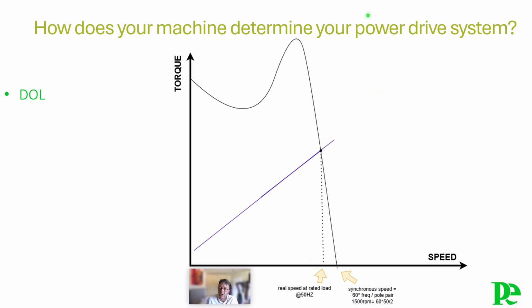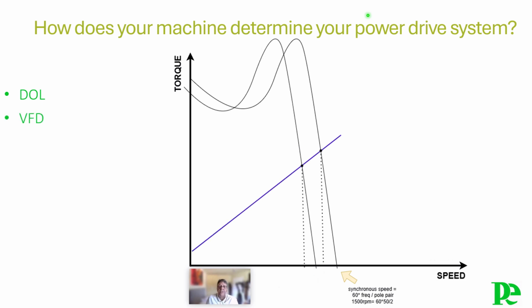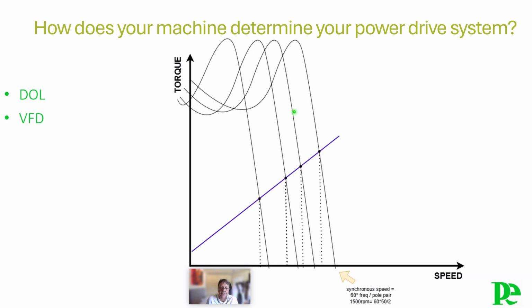And in the case of an asynchronous motor, this speed is some percentages lower than the synchronous speed due to the motor's inherent slip. In the following diagram, we will show the effect of a variable frequency drive driving the motor. It becomes clear that changing the frequency will result in another synchronous speed and therefore also in another speed of the driven machine. The sinusoidal waveform produced by the variable frequency drive, which has an adjustable amplitude and frequency, allows for variation in the speed of the machine as shown in the diagram.